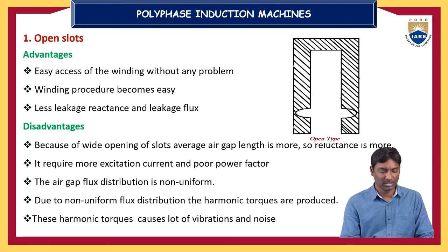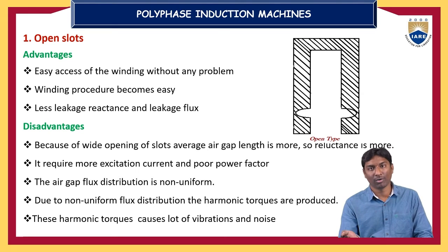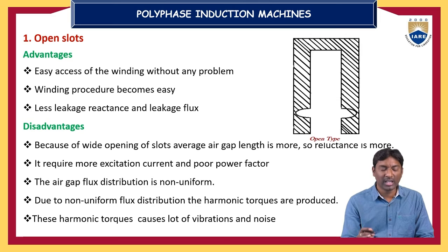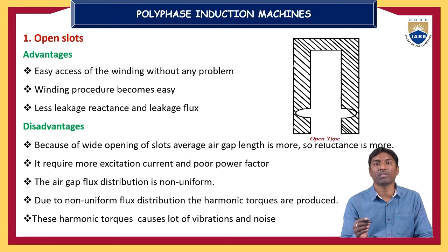The leakage flux will be linked with either the stator or the rotor, but not both. The leakage flux affects the inductive reactance, and due to this effect on the inductive reactance, the performance of the induction motor will decrease. That is a disadvantage of open slots.